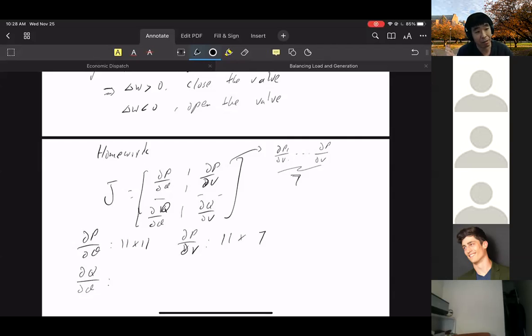The active power from the generator is given, right? We know the number. Column B is the active power given to you for a PV bus. But column C has the reactive power. For a PV bus, the reactive power is not set in the beginning. The PV bus is only P and V. The reactive power is not set. So how many Qs do we have?